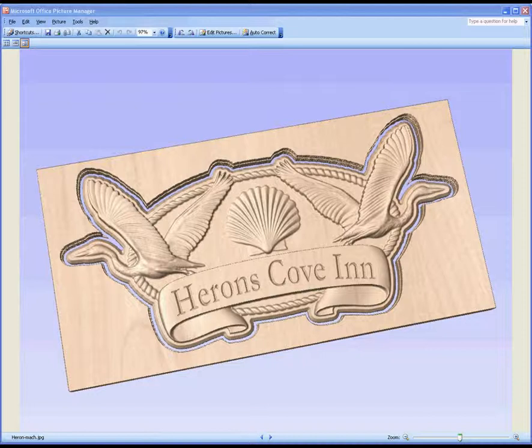So we're going to go through similar steps to those we've been through in the other machining tutorials, that is, create the border vectors, do the offsets we need, and create the area that we're going to do the 3D carving in. We're going to generate a roughing and finishing toolpath. This time though we're going to add a V-carving toolpath that's going to be projected onto the banner to do the text. Finally we'll do a cutout pass, and that'll finish up this particular example.